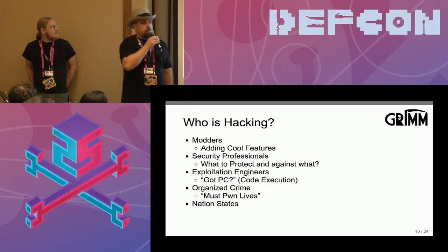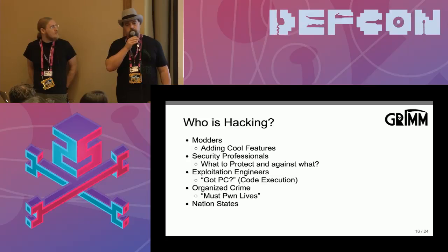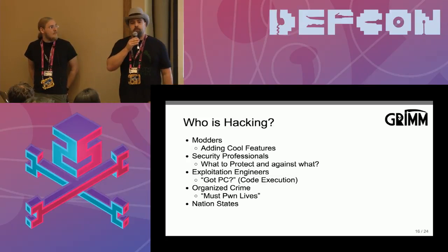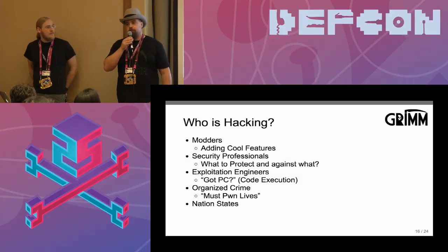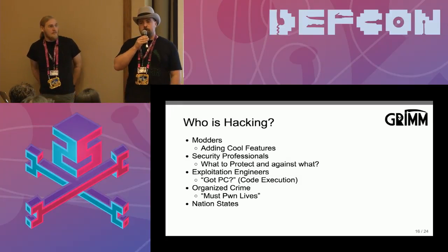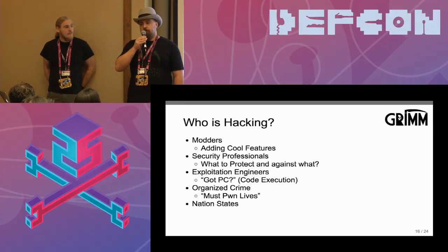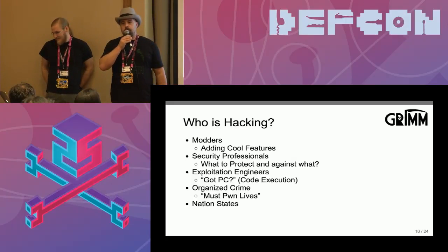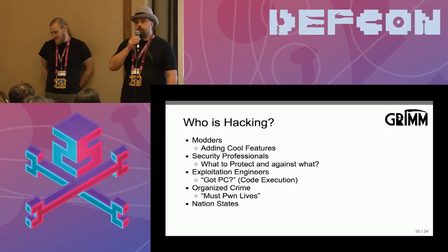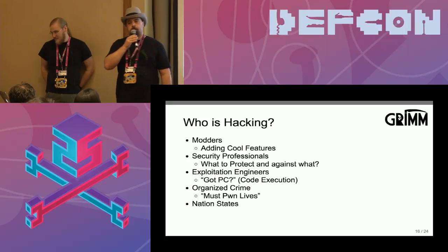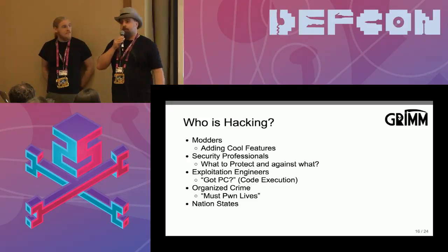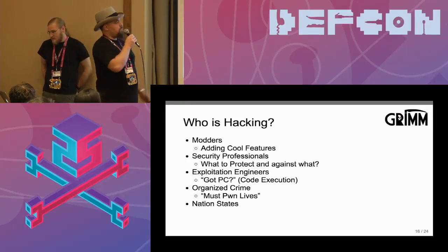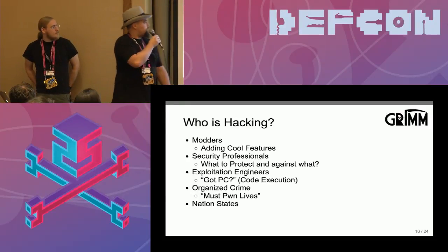Exploit engineers, code execution. As I said, these are often very, very small micros. They're not running an operating system. There's no data execution prevention. There's no ASLR. If you find a buffer overflow, you stick your shellcode on the stack, overwrite the program counter, and jump to it. It's back to the 90s in terms of security, because these small processors in use just don't have these features. There is no operating system in use to add these features.